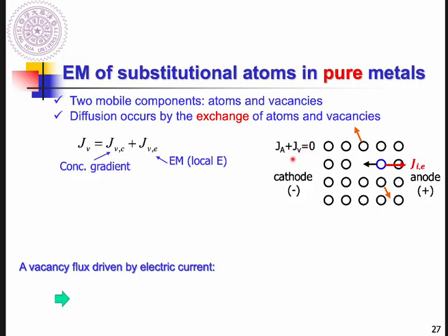As long as you have a vacancy flux, you can probably visualize it through void formation, forming small voids and large voids. And as long as you can visualize the void, you can estimate its volume. This is how we analyze the magnitude of the vacancy flux. Because we cannot directly measure JA, we use JV instead.